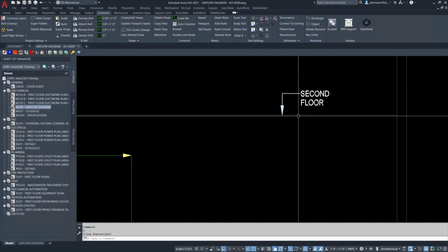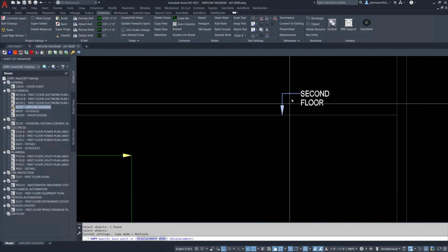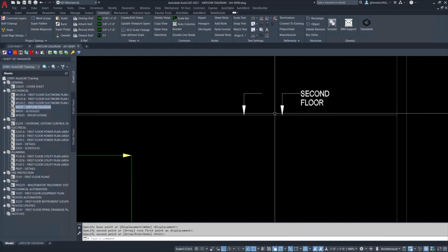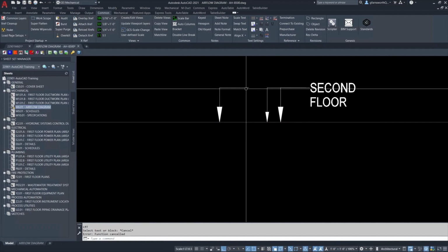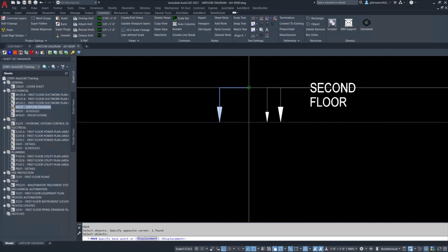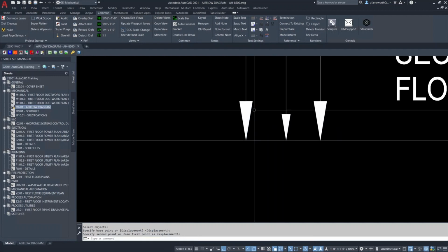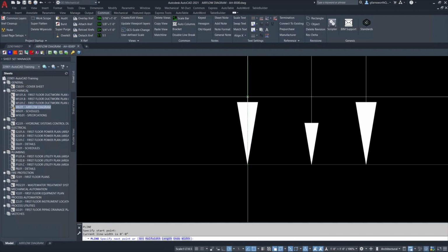In AutoCAD, you can change the thickness of a line using polylines, but Revit doesn't have polylines. Instead, in Revit, line thicknesses are controlled by object styles. So if you import a thick polyline into Revit, it won't be any thicker than its object style. This is a particular problem for some leaders and home runs, where the arrow is a tapered polyline.